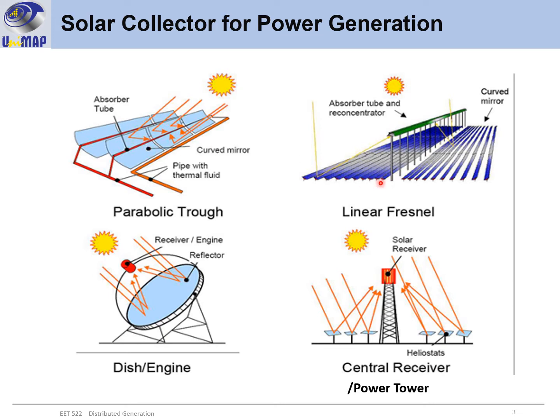The second technology is the Linear Fresnel. It's a little bit different from this one. You have a long pipe in the middle, and they have curved mirrors located at both sides. These mirrors will receive the solar radiation, and the solar radiation will be focused on the center pipe here.